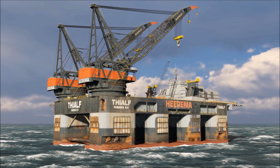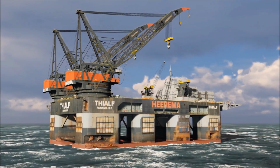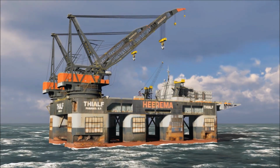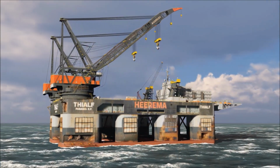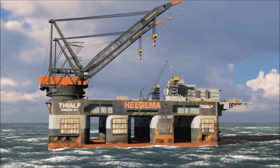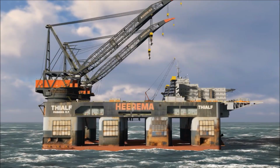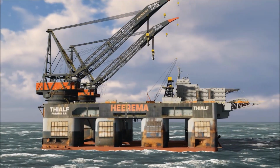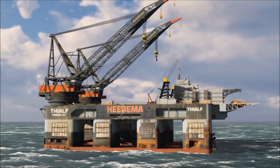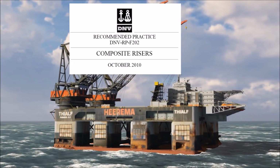So one structure for which there has been considerable development work is composite risers. The design requirements for this application include a 150 year fatigue life. So you can see the level of conservatism, which is 10 times the service life. If your service life in this case is 15 years, you should design your structure for a fatigue life of 150 years. The connection between the tubes is critical.